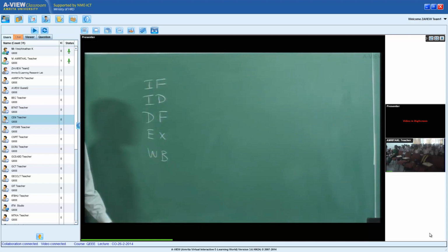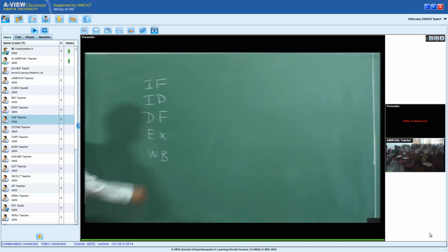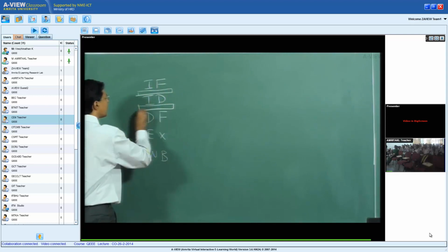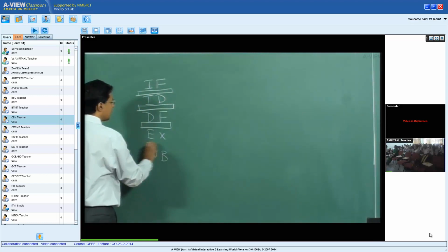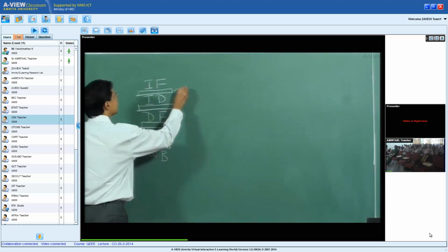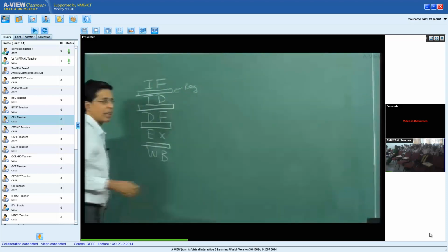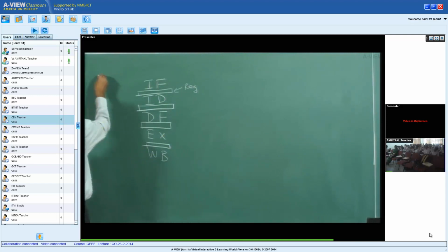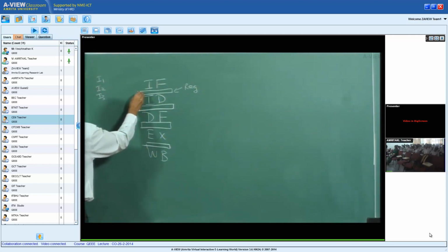Last class we saw these stages, and we also understood that we will have registers in between so that these stages are isolated. Let me assume there are, say, 3 instructions. I1 is fetched. When I1 is decoded, I2 is fetched.